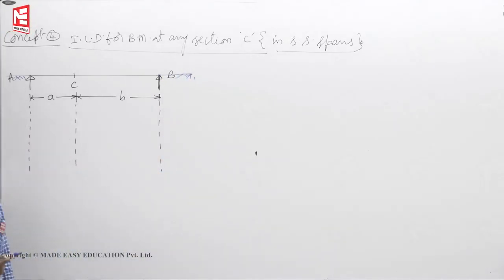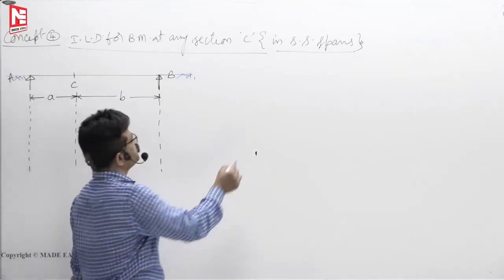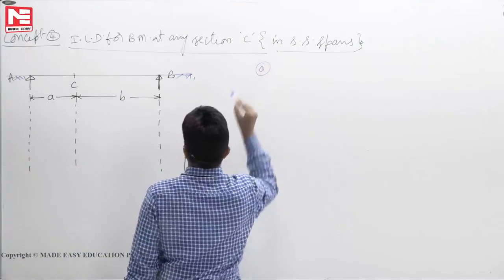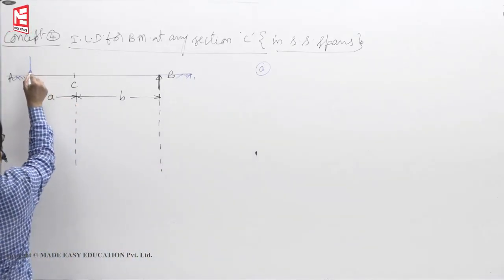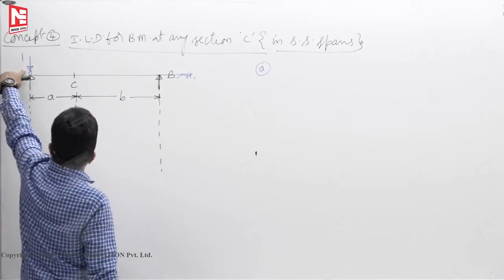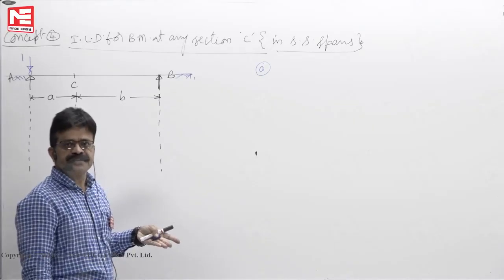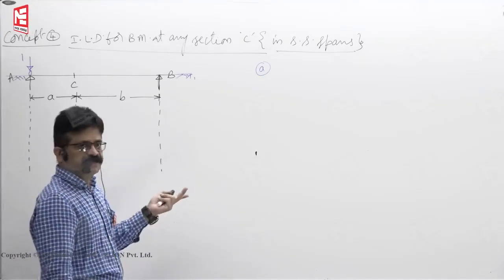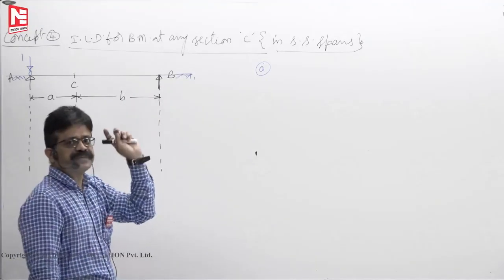First we will take the strength of materials concept here also, then we will see how to save the time. When the load is exactly at A, what's the bending moment? Because load is at A means the direct transfer of load to the support happens. So VA is 1. So bending moment at C means it is not at all taking the load. So bending moment is 0.